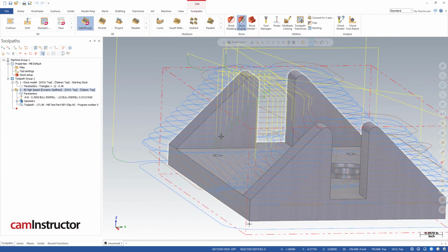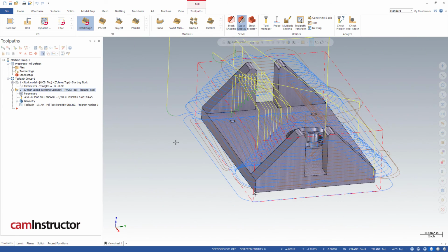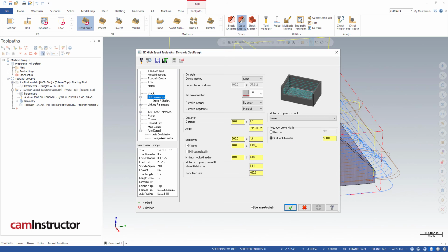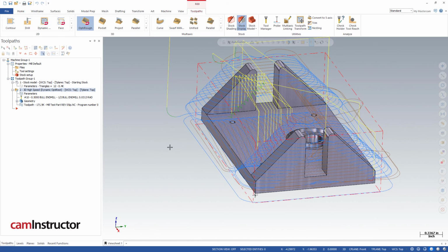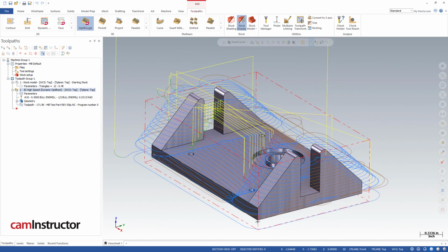We're still probably going to do a semi-finishing toolpath on these surfaces with a 3D toolpath. Or you could refine these step ups to negate the fact that you need a semi-finish operation for the surface toolpath. I'm going to stick with this. This tool is just going to rough this thing out, get the material out of the way, and we'll get into our finishing toolpaths after that.